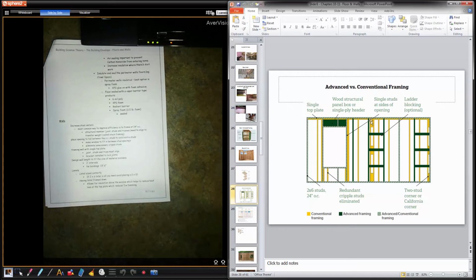Or again, the 2x6 on the flat is an energy efficient way. So the way we do it in the shop, 2x6 on the flat. Instead of going with 2x6, you could go with a 1x6 to get more insulation in that space. And the key is insulate later, so it doesn't get wet during construction. So quite a bit of savings just on material. But the key is more insulation. Like you see, every time there's a stud there, there's less spot for insulation. Everything gets a little bit tighter.